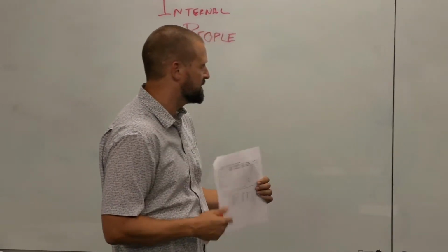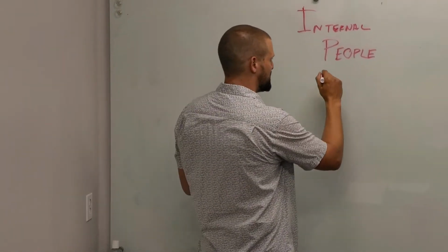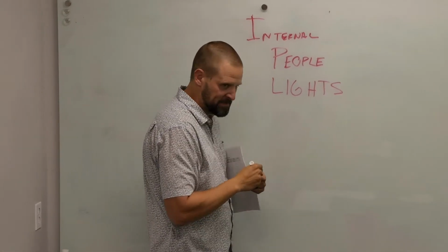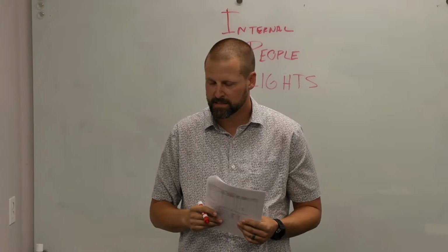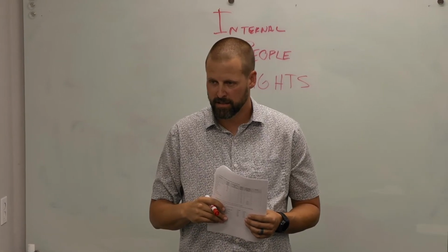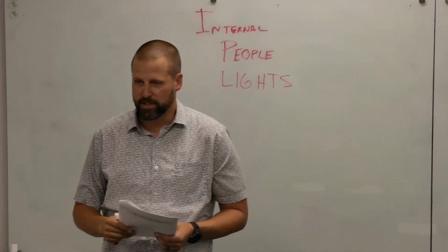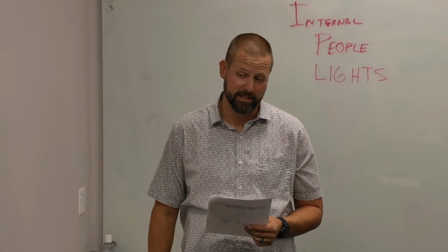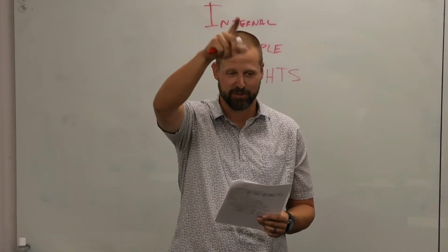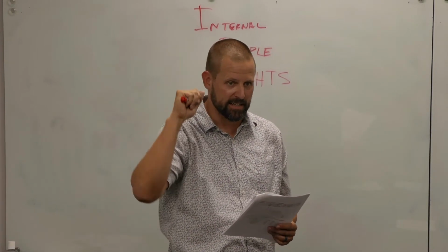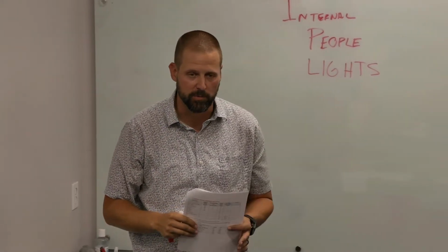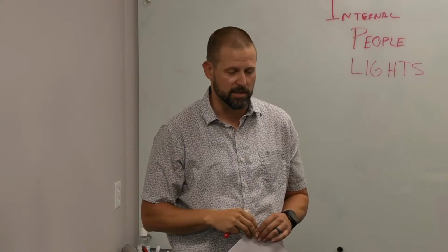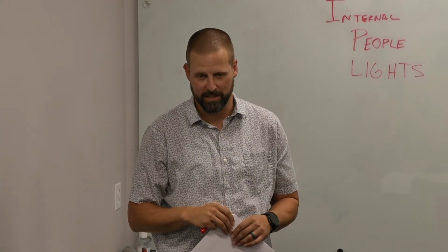Okay, what about lights? I'm going to write this down so I have something to do. You can directly take the wattage output. Yeah. So we could look at the electrical plans, and we could look at the schedules, and I'm not even going to describe this right because I've never done it, but we could get the actual lighting and use that for a space. Generally what we do is use some sort of watts per square foot that is either equal to the code allowance for that space or something bigger.